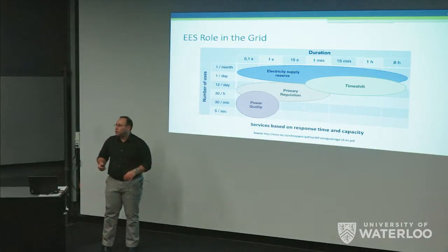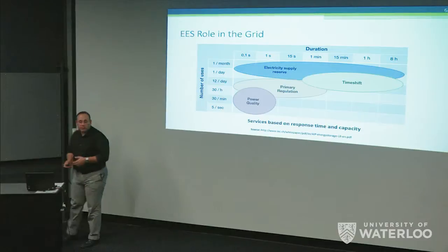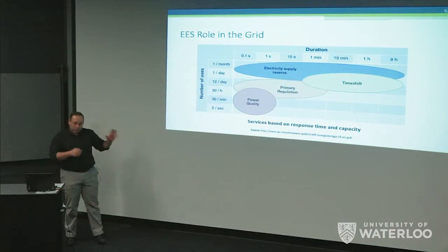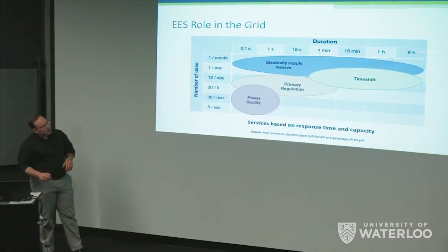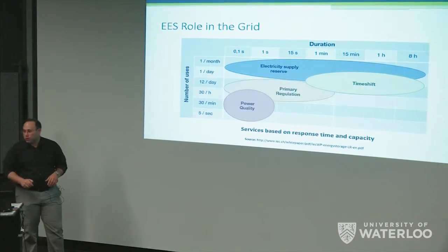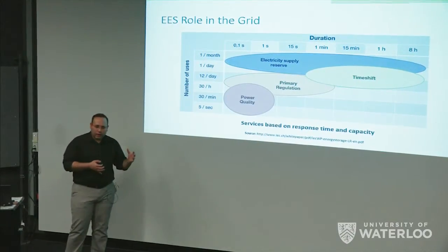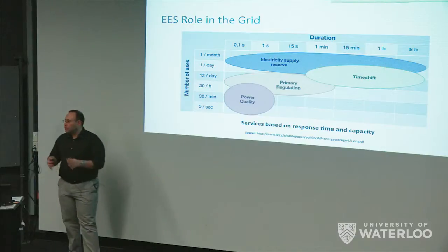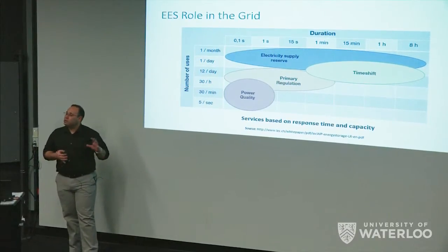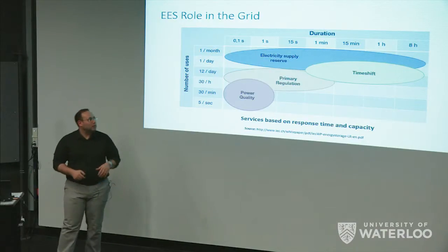Those are the services that you provide with ultracapacitors, some batteries, and some flywheels can operate around here too. Then time shift, and this part is bulk energy. That's where you have big storage. You can use pumped hydro. Realistically, batteries would not be suited for that, even though they were kind of shifting toward it and they advertise it that way.